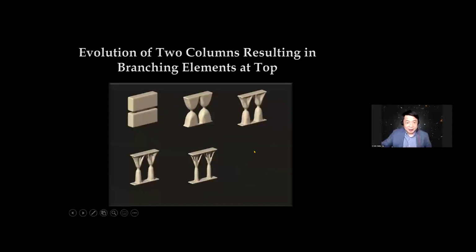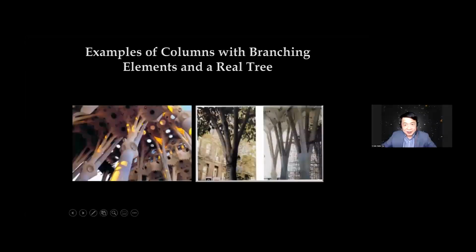We also did some 3D models. So these are trying to design 2 columns on a flat surface. Starting from this initial design, every step we remove the material with the highest tensile stress, and then we would arrive at some odd shape like this. It looks like tree branches. It might seem very strange to get this shape, but if you look at the main column inside the Sagrada Familia Church, they're almost the same. You can see these tree branches within the main columns as well.